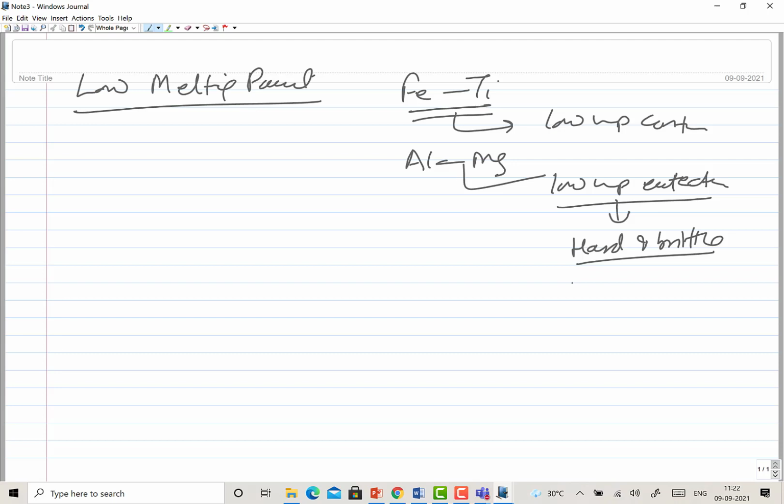So we must consider this possibility. We must avoid the conditions under which these low melting point phases are formed, or we should try to avoid such combinations or direct interfacing of combinations leading to the formation of low melting point constituents. We can also use suitable films at the interface or interlayers, or use a transition joint, if that is not workable.